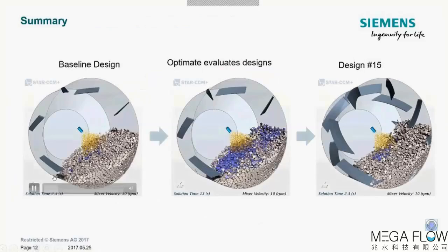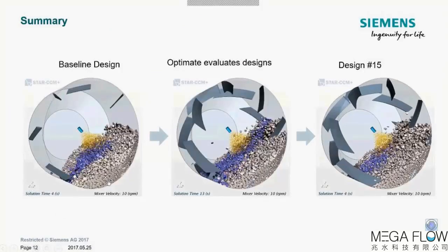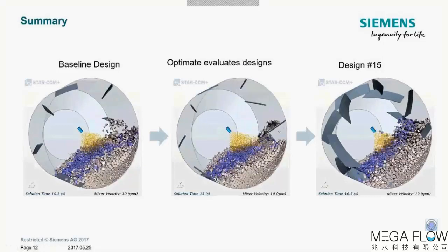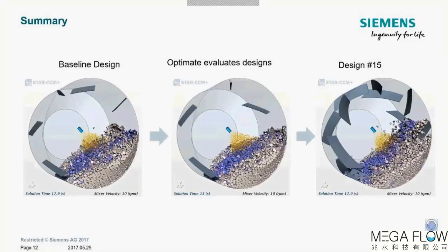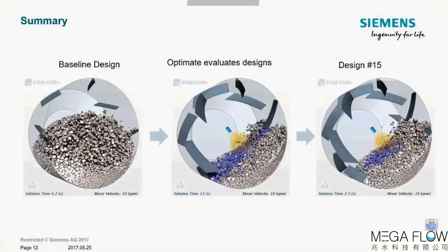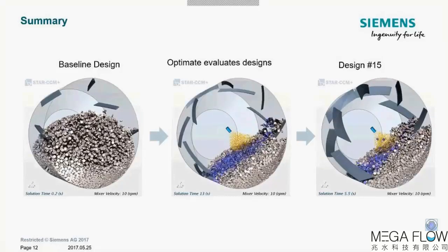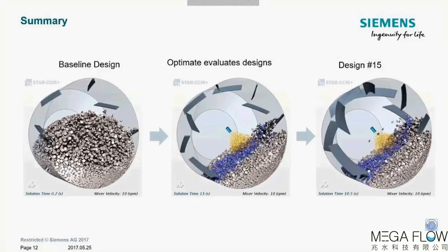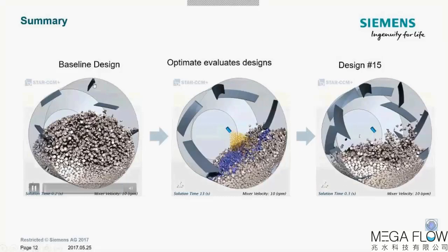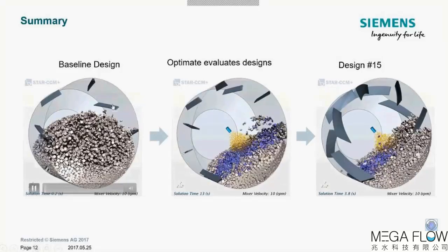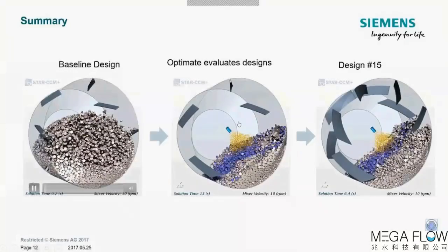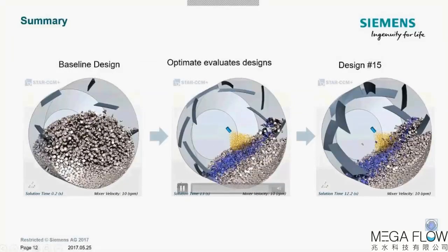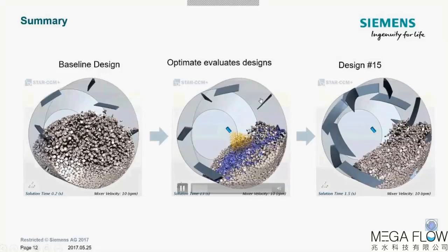So here's a summary slide. I want to say that we show how to set up the basic coating simulation in STAR-CCM+, and then how to let the Optimate option of STAR-CCM+ do the automatic design exploration and find the best values for the height of baffles, the number of baffles, and the angle of baffles, which will provide the maximum coating rate and the minimum tablet particle damage in your equipment.